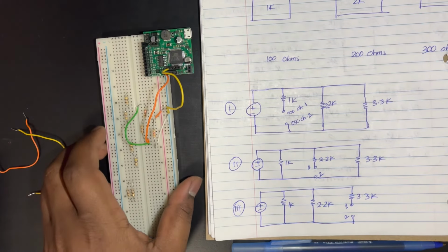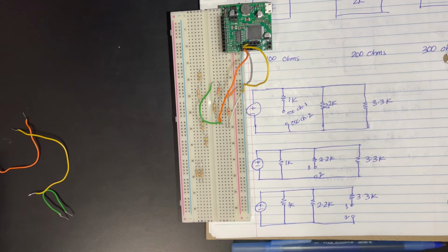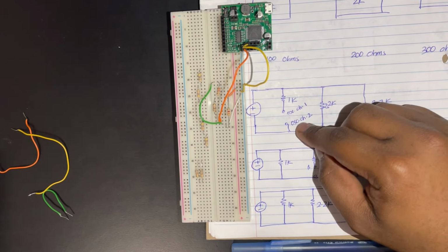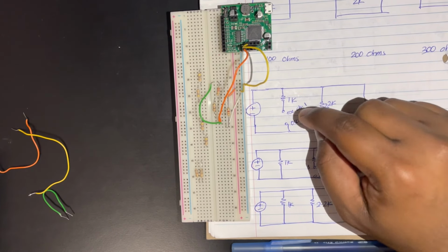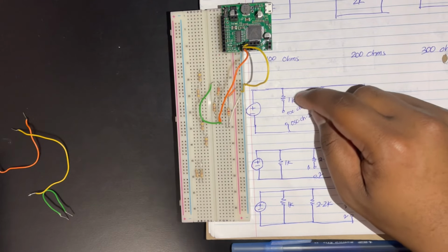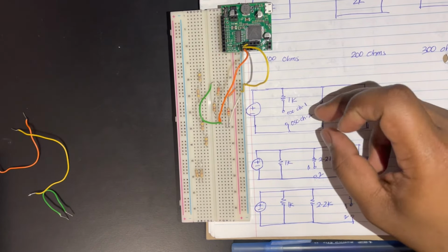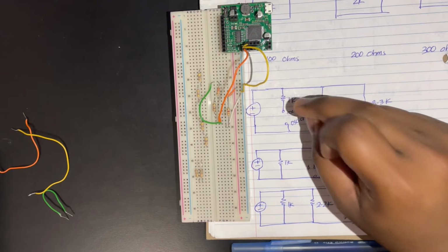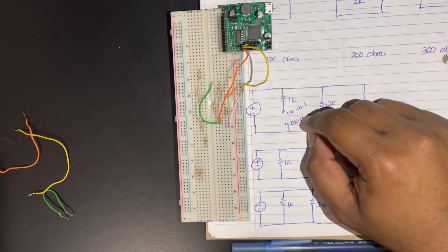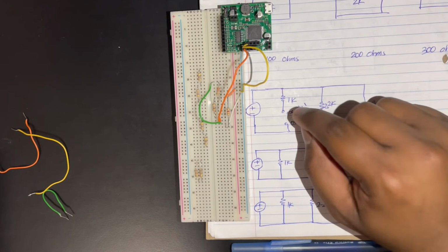So now that I did this, if you remember, when I connect this one, not only do I have to do this, but I also have to connect 10% of the resistance across which I'm measuring the current. 10% of the resistance value has to be connected in parallel with oscilloscope channel 1 and 2, right? If you remember, I have 1K over here.